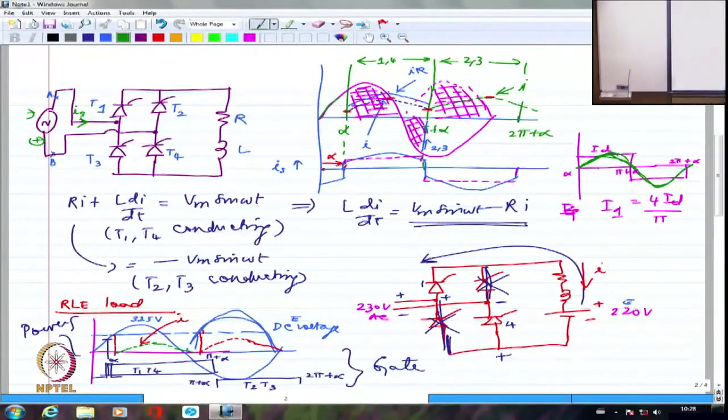So this is the phase shift between the current and the voltage. And if I look at this current and the fundamental current, both of them are actually not phase shifted. They are in phase with each other. So I can say the fundamental current and the fundamental voltage are shifted from each other also by an angle of alpha.